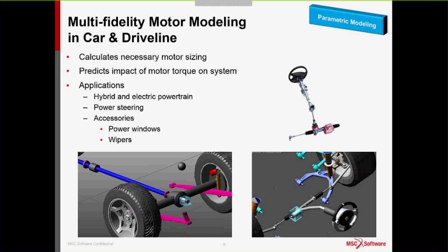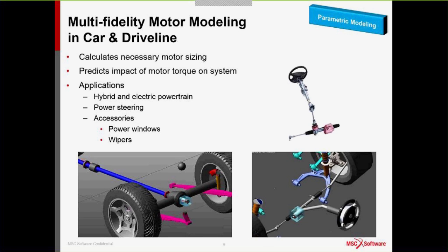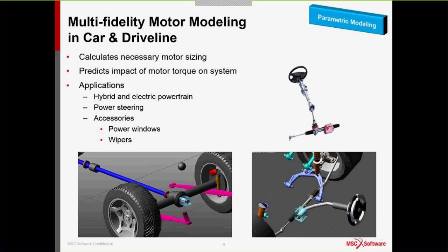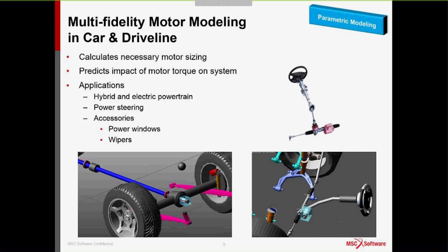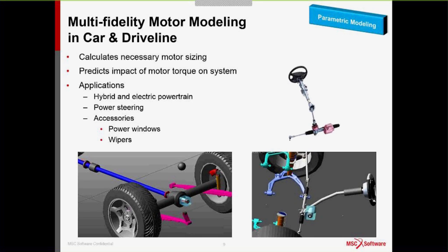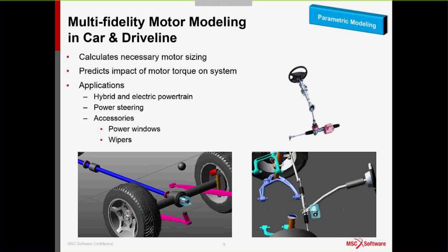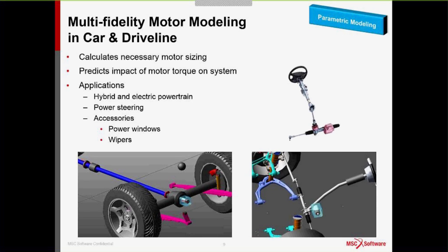So we've provided four different motor types, specific electric motor types, and it's a wizard-driven environment. So basically, you input some of the key parameters depending upon the type of electric motor and the complexity of the motor that you want to reproduce. And then the electric motor module will put the component together.